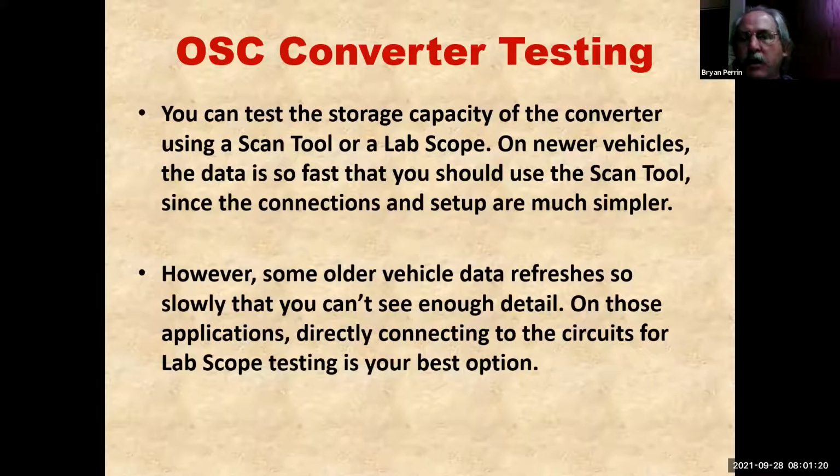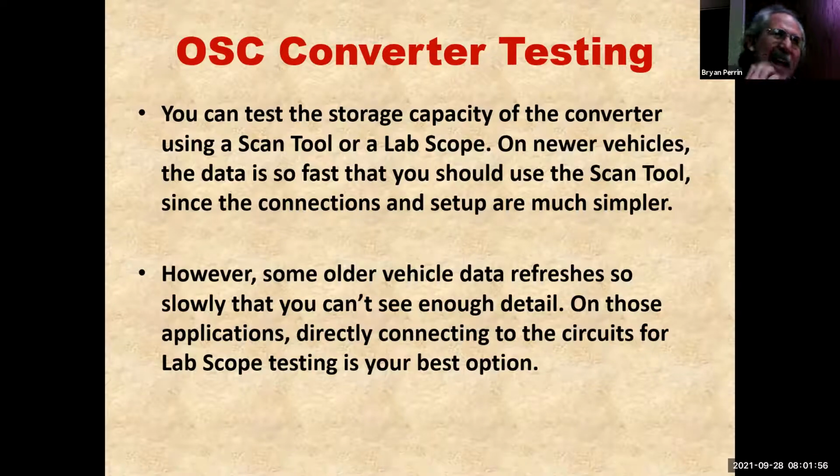We talked yesterday about converter function a little bit, especially for the purpose of testing, that we need to make sure our O2 sensors work or our converter won't work. And then we looked at the ways that manufacturers use to run the cat converter monitor, which is either switch ratio testing to infer oxygen storage of the cerium, or direct testing using oxygen storage capacity directly to measure the cerium inside the converter, because we know cerium is the material that melts at the lowest temperature. So it's kind of like the fuse inside our converter. If a converter has a problem, it's the element that goes away first. So today we're going to talk about us performing an OSC test.